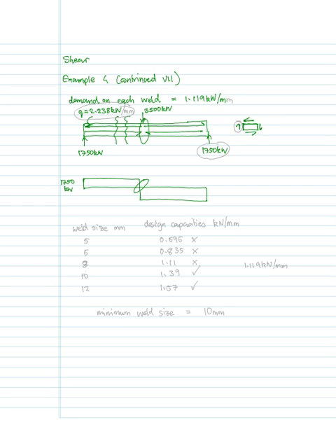And if you converted that into a force, you would probably find that the majority of the 1750 is being carried by the web, and a small amount has been calculated by the flanges, which you could calculate if you wanted. And then if we did a cut on the other side to the right of the 3500, you would find exactly the same, but in the opposite direction.